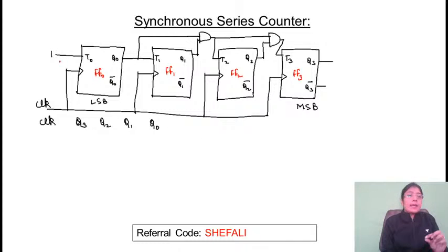So every time, since this is a toggle flip-flop and this is connected with the input 1, तो इसका मतलब क्या है? जो आपके पास flip-flop 0 है, that will always toggle. Flip-flop 0 toggle करेगा, meaning हमेशा Q0 की value हर एक subsequent cycle में toggle करेगी. T की value if it is 1, तो अगर आपके पास previous output 0 है, then in the next case you will be getting the output as 1. If the previous output is 1, in the next case you will be getting the output as 0. Make sense? Now here, if for clock 0 inputs are 0,